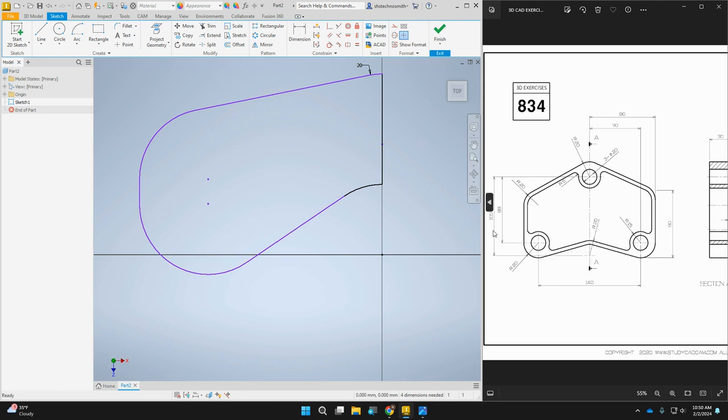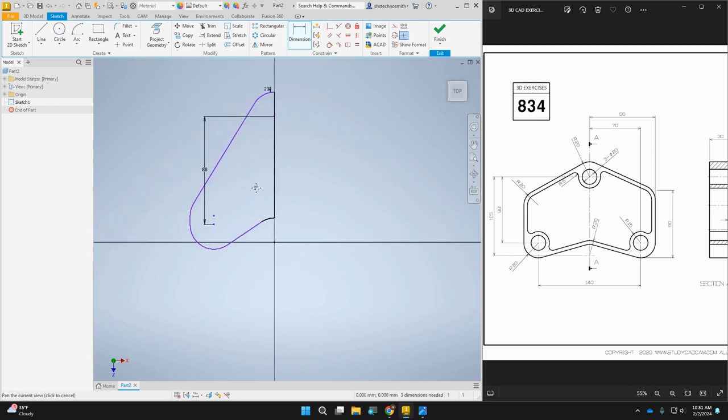Because we're doing half of this, and one of the reasons why we did all the arcs instead of adding fillets is because most of the dimensions in this drawing are referenced off of center points, we need those center points in order to draw it. This bottom circle and arc here, there's only one center point there, so they all share the same one. It's 88 millimeters from the middle. The center point for my top arc, that's this one here to there, it's 88. So it's going to stretch it way out.